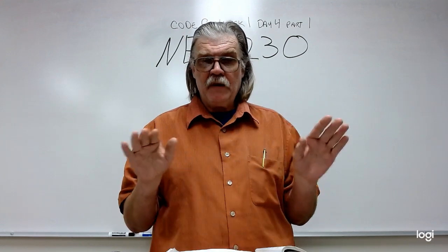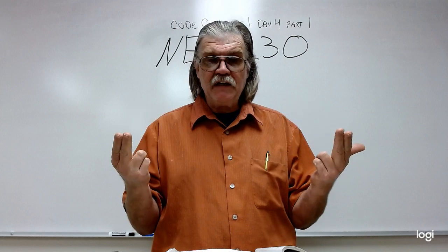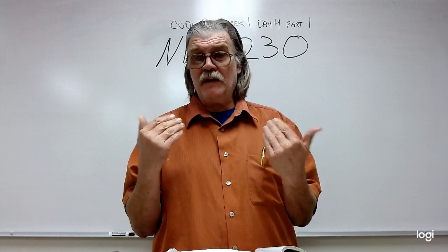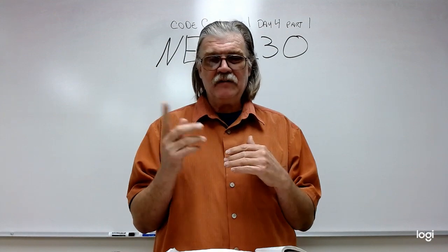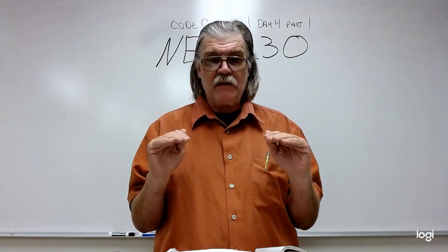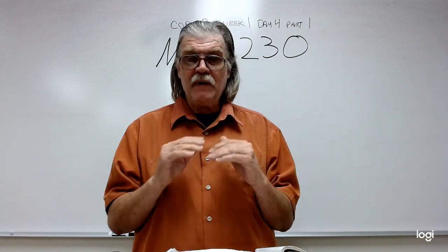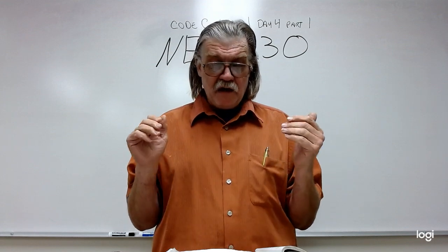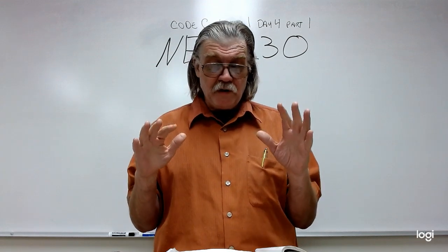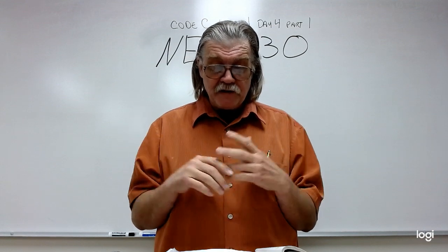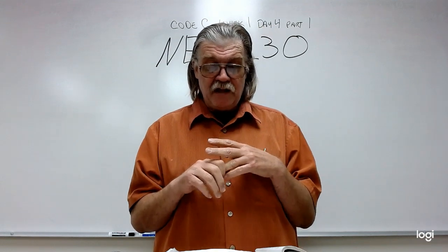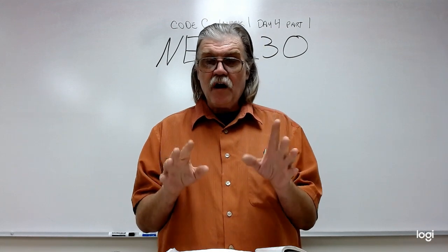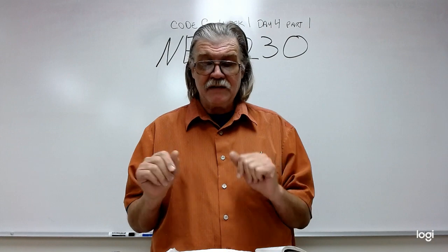Okay, if you do a panel change, you will definitely have to make sure you're doing at least a 100 amp service. I recommend on any homes that you're doing, do 200 amps. But that's not what the code requires. Code requires 100 amp minimum for one family dwellings. And then we have D, all others. And this is kind of a little weird one. It says for all other installations, the service disconnecting means shall have a rating of not less than 60 amps. That's all others, not less than 60 amps, right?